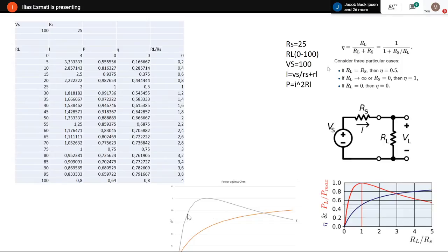Again, this is a theoretical example right now, but we can do it physically, of course. Then you can see that I can plot. If I plot resistance as a function of power, I get something like this. And you can see that at some resistance, you get the maximum power. What does it mean? It means if you choose your load resistance at the point where you have the maximum peak, then that's the maximum power. That's the fine tuning, and that's the beauty of it.